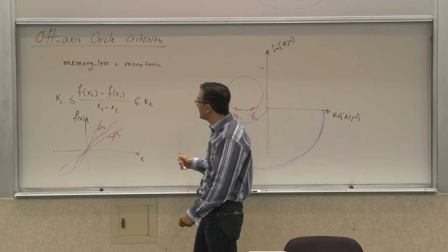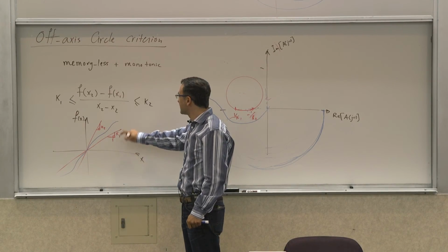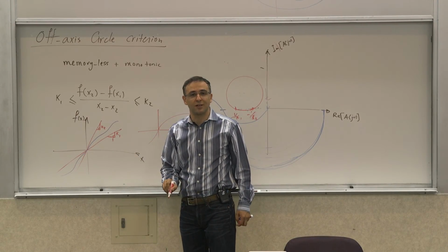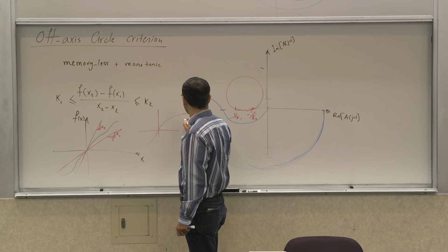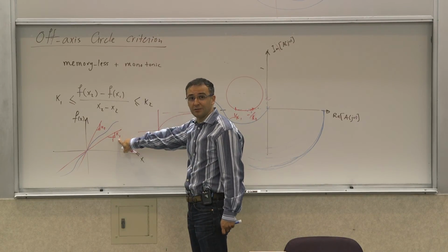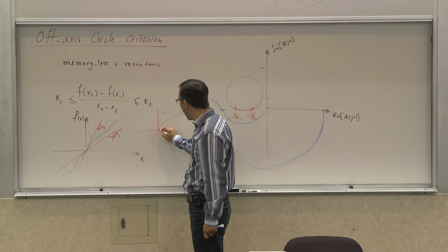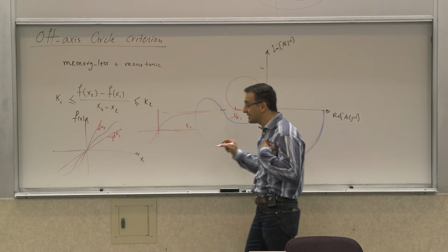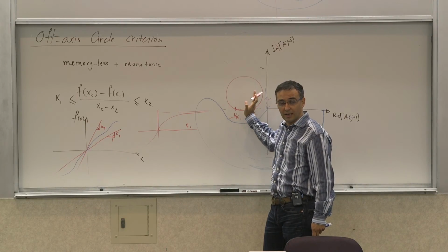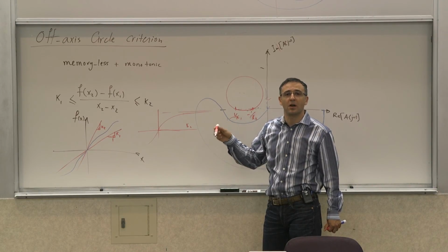Actually, that gives you some interesting design insights. For example, let's say you have a nonlinearity that saturates. We've seen the hyperbolic tangent for the bipolar transistor differential pairs, right? The problem with this hyperbolic tangent is that there's an asymptote with a slope of 0, so there's no K1 value greater than 0 that will satisfy this, right? So you have to set your K1 to 0, which means you have a point here that you need to avoid. You have to pass a line, and it limits a lot of things. So a lot of those conditionally stable systems become unstable.